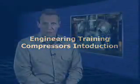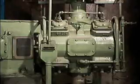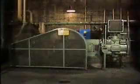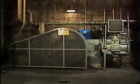Compressors fall into two general categories: positive displacement compressors and dynamic or centrifugal compressors. Positive displacement compressors work by trapping a certain amount of gas and forcing it into a smaller volume. A common type of positive displacement compressor is a reciprocating compressor.